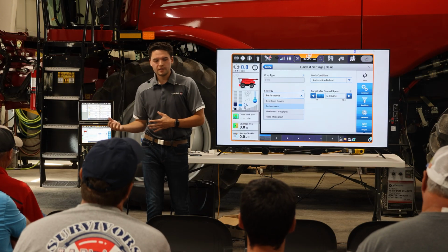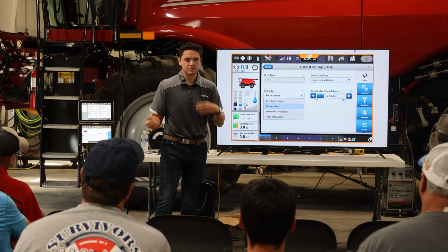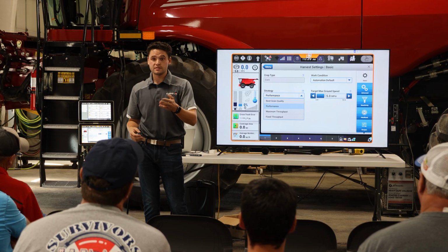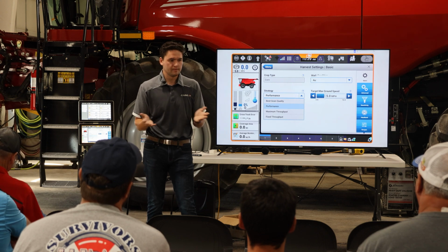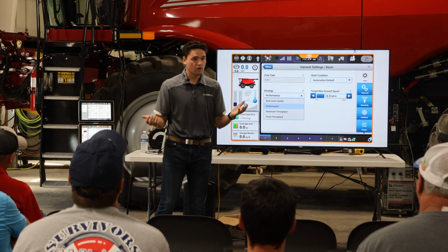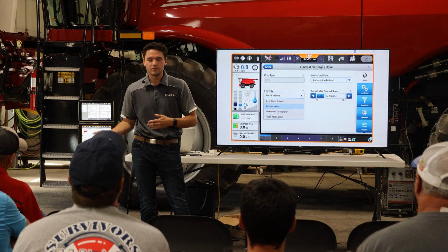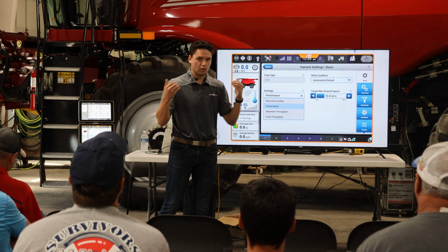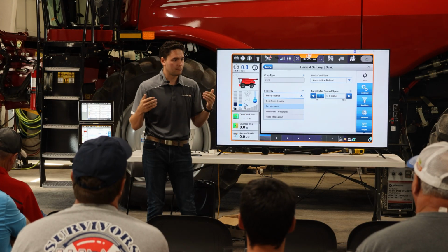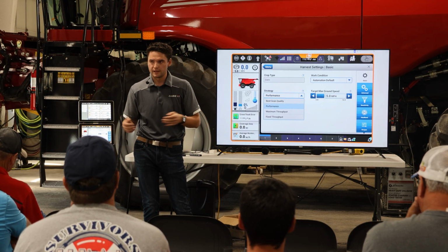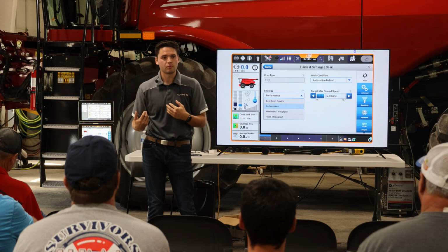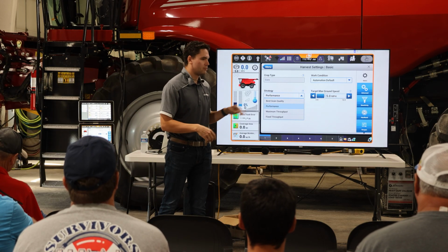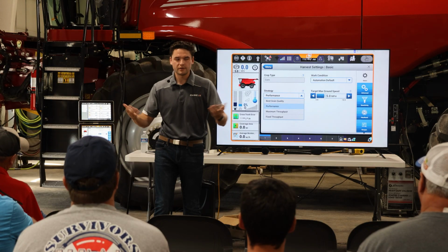So to understand that, we probably need to know what are we trying to harvest, what is the outcome here. So in your seed beans and things like that, absolutely your best grain quality is probably your best, because you have a higher dockage and you make more money by having a better sample, right? But if you're sending to, let's say, an ethanol plant on corn, where you have a higher percentage of MOG and broken grain you can send in, and it's simply about the more weight that I can get, right? Because the more pounds per acre I get, the more weight that I get, or the more money that I get. So why wouldn't I be willing to prioritize losses to capture more of my crop and accept a certain percentage of MOG and broken grain and get more value out of that?